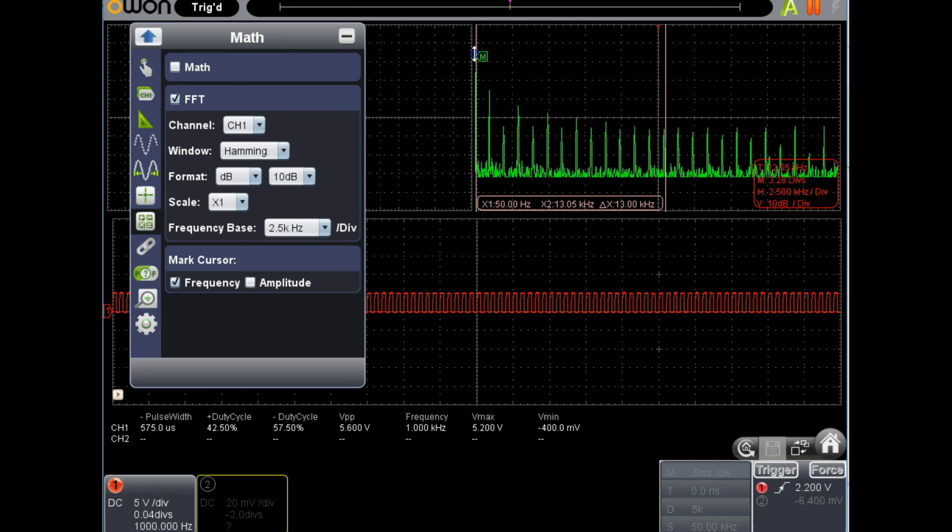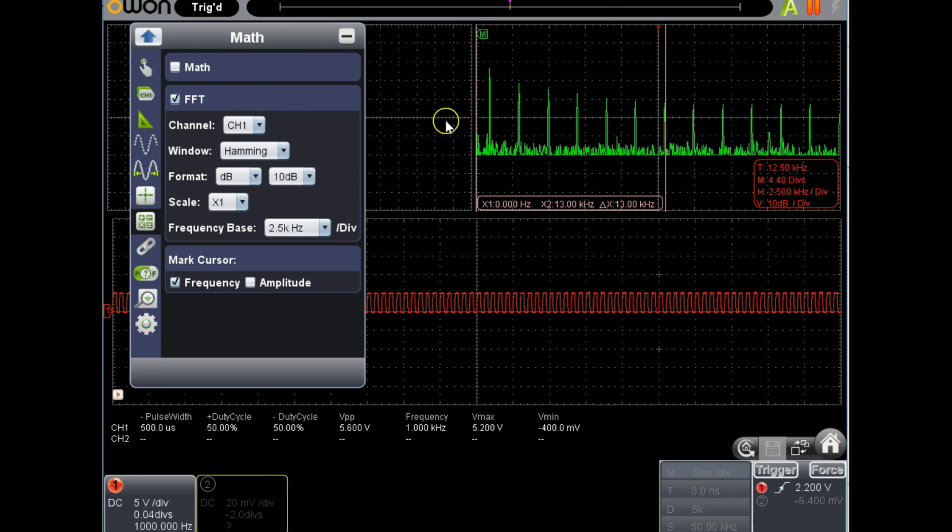Well, this is the amplitude of those peaks relative to this marker here in decibels, so it's actually negative going down from here, and the unit of decibels are defined as 20 log to the base 10 of the ratio of this amplitude to the origin here. 20 log 10 because it's conventional in electronics to take power ratios which go like the square of voltages.